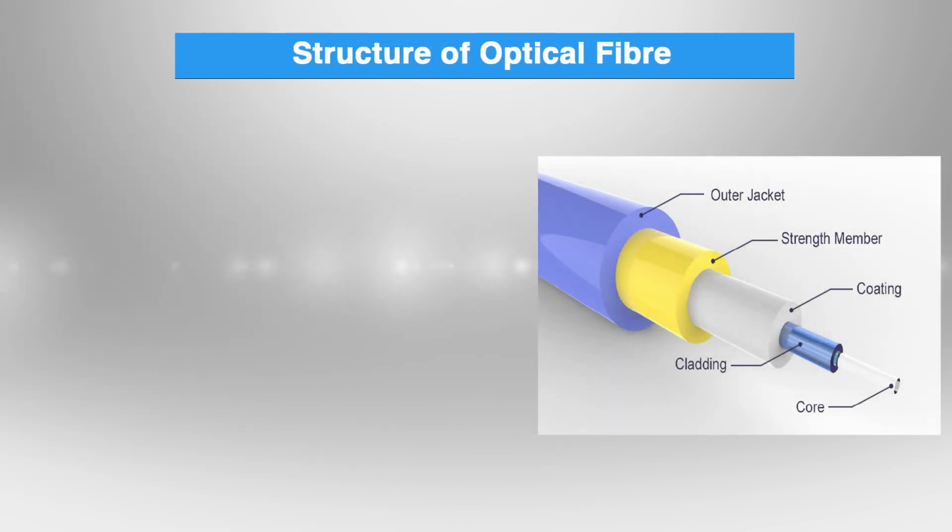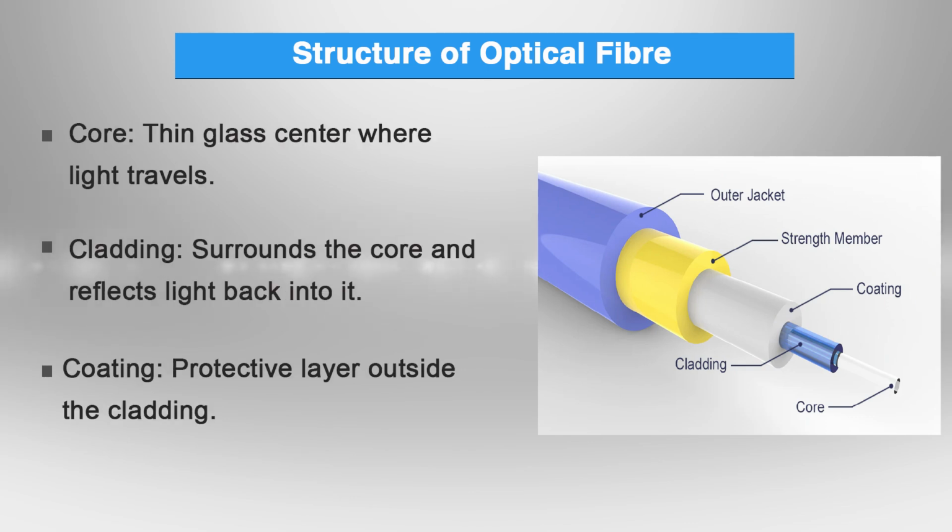Now, let us consider the structure of an optical fiber. A fiber optic cable consists of 4 parts, namely core, cladding, buffer and the outermost layer as jacket. The core of a fiber cable is a cylinder of plastic that runs all along the fiber cable's length and offers protection with the help of cladding. The diameter of the core depends on the application used. Due to internal reflection, the light travelling within the core reflects at the core-cladding boundary. The core cross section needs to be circular for most of the applications.